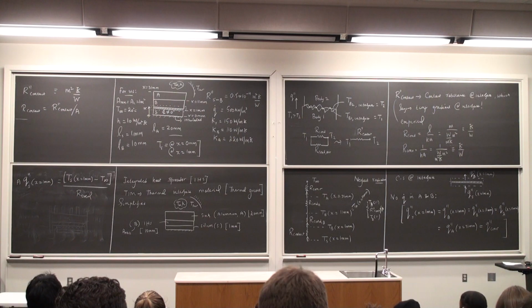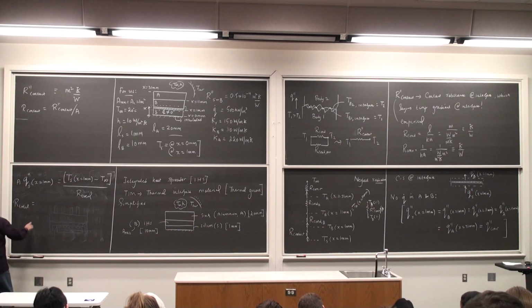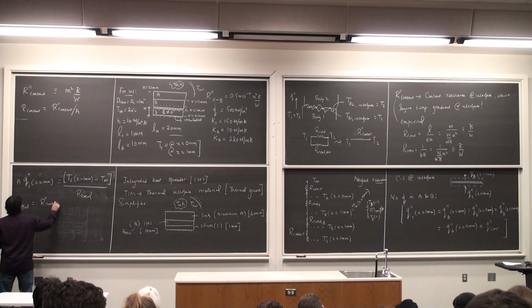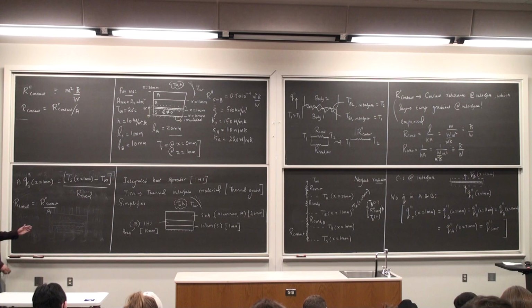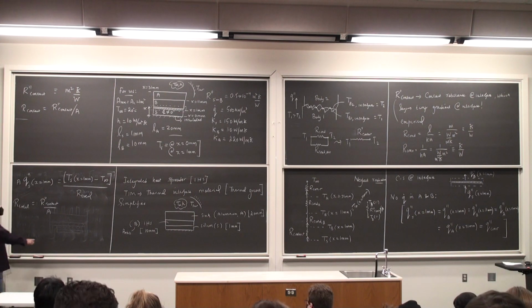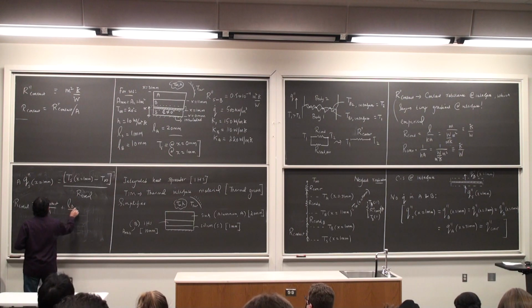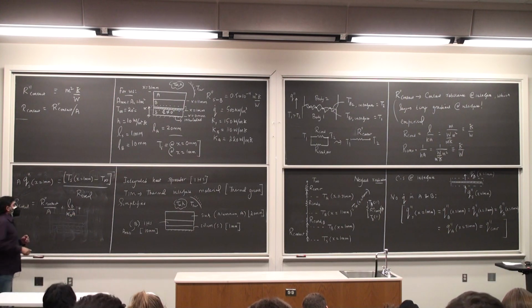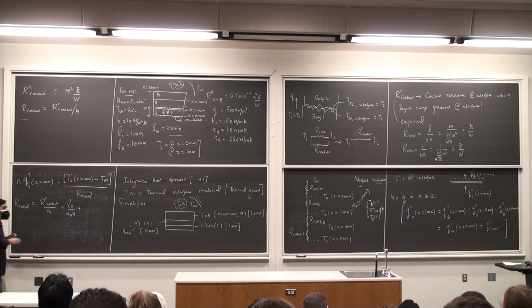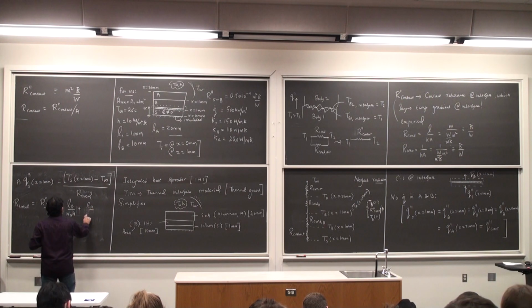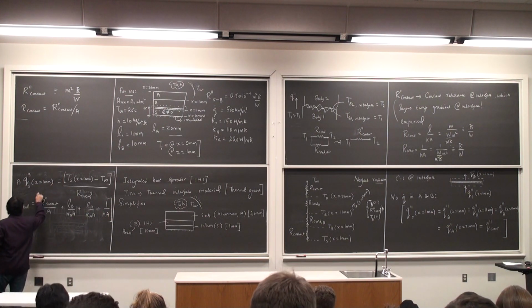So that's one equation. I don't know anything about any of these things except R total. So let me write R total. It is the contact resistance, first of all, divided by area. Don't forget to divide by area. In this problem, the area is 1 meter square. It need not be the case in any of the other problems. Okay? Plus, I'm going to have conductor resistance. So that's going to be LB by KB times A. In reality, as one of you mentioned, there should be another contact resistance between B and A at the interface, but I'm ignoring it. So this is just going to be LA by KA times A, plus 1 by H times A.